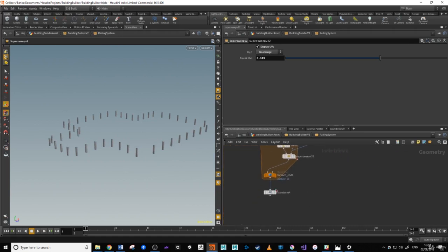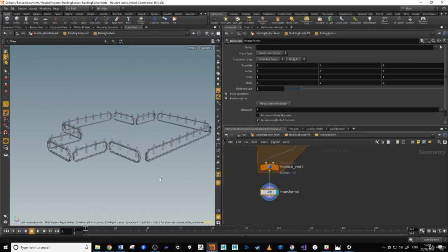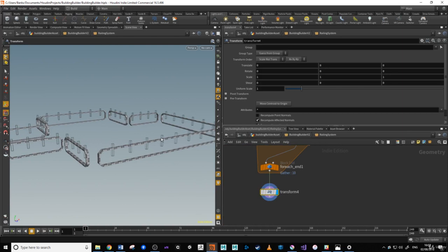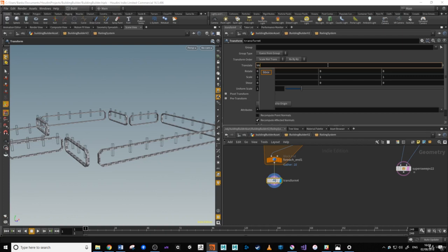So what we can do is we can tell our frame to position itself at the maximum of the bounding box of this object. Okay, and again, we'll go through it, I'll step through it, but I will type it out initially and then we'll discuss what is going on with the expression. So in the transform node of the frame, we're going to type bounding box or bbox, and be careful, it is bbox, it's not box or bb box, it's bbox.